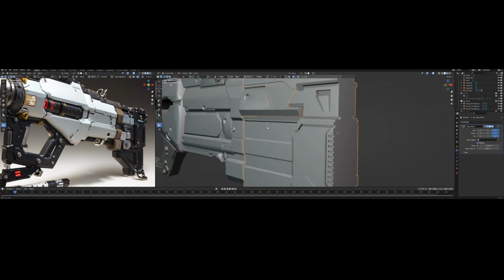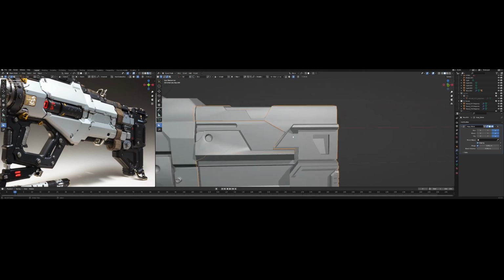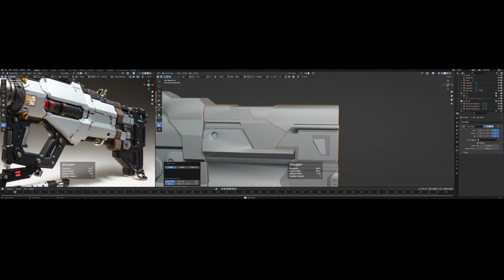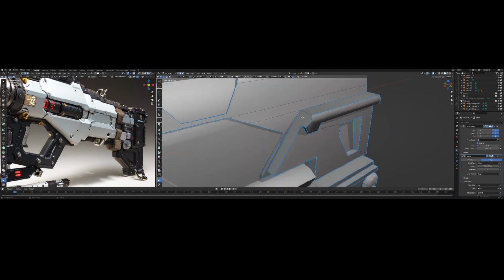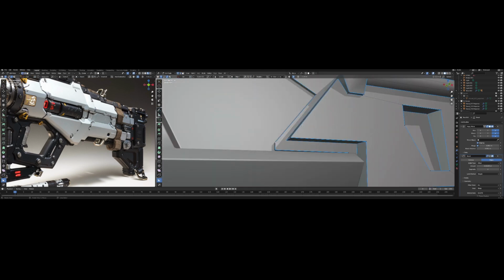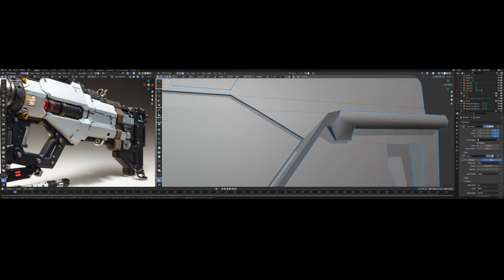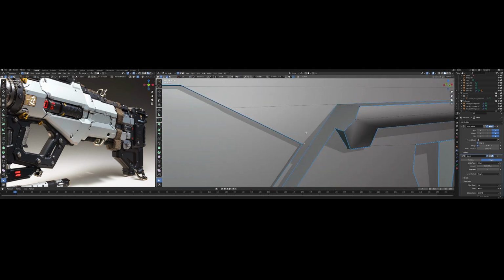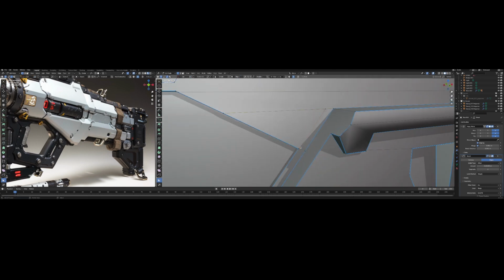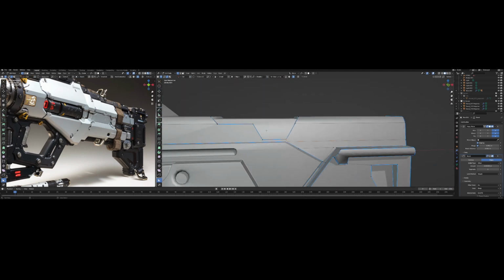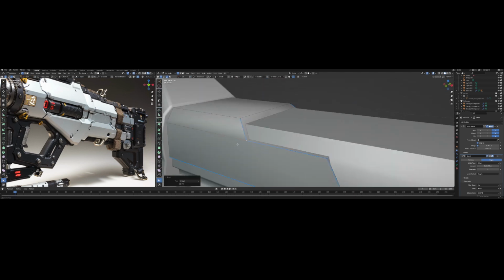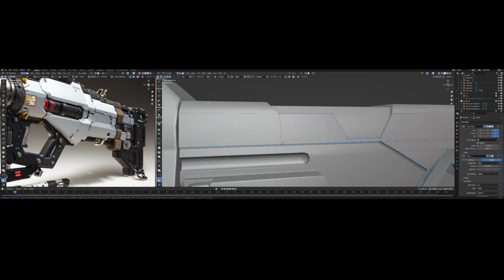So that's the reason I think one of the important steps, just after we have cut or sliced all those things and applied the boolean, is to go to clean mesh. It will remove all the single vertices, unnecessary edges, and the duplicated vertices. So we can start solving the shading problems again.